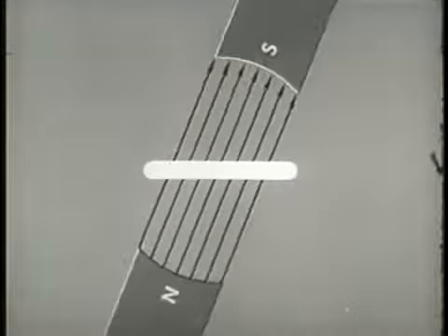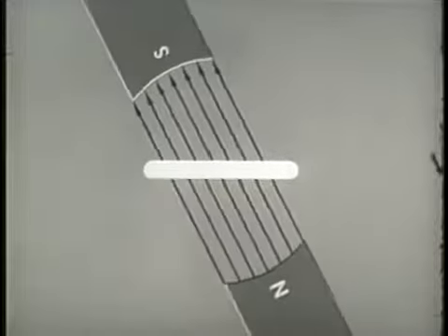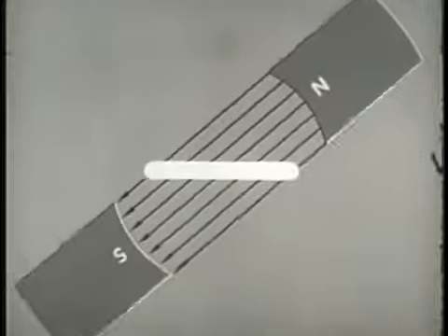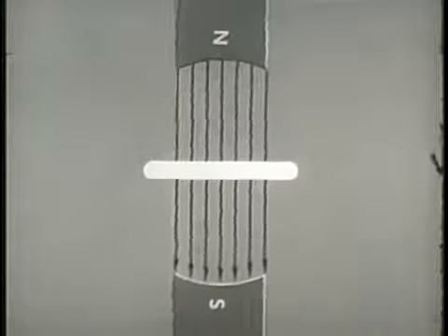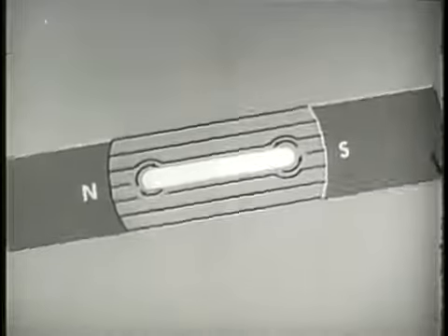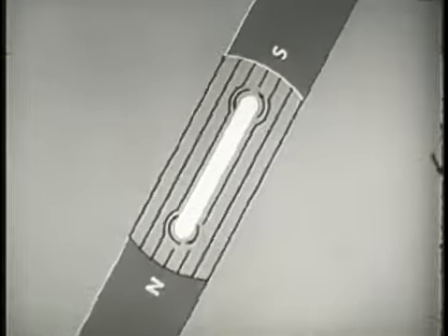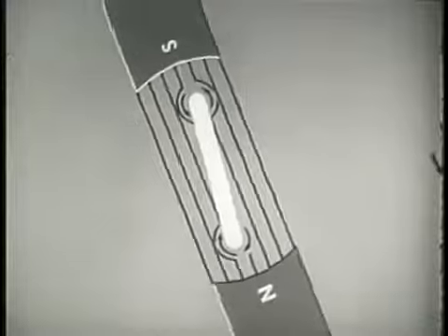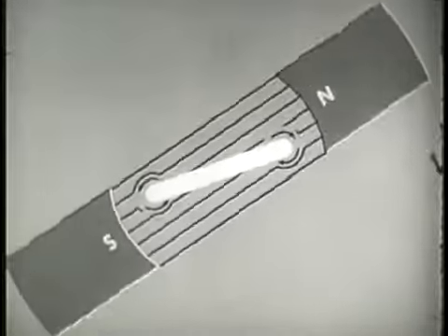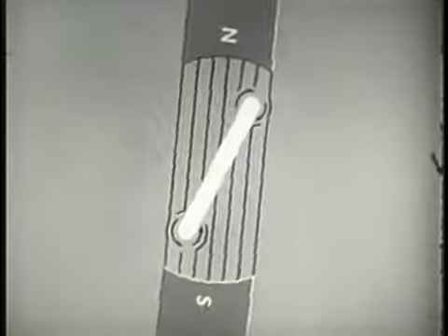This, however, is an impossible situation, for if the rotor stops while the field continues to turn, relative motion will have been re-established. Lines of force are being cut once more. An EMF is generated and the resultant magnetic field will cause the rotor to move again. So far, we have rotated the field by physical means, which is impractical. It is necessary to find a way to rotate the field electrically.